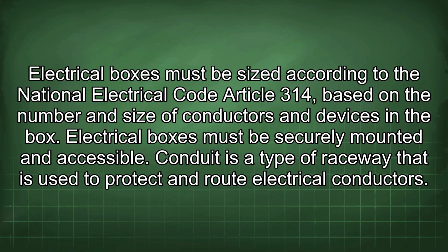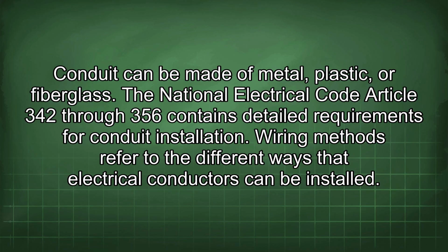Conduit is a type of raceway that is used to protect and route electrical conductors. Conduit can be made of metal, plastic, or fiberglass. The National Electrical Code Articles 342 through 356 contain detailed requirements for conduit installation.